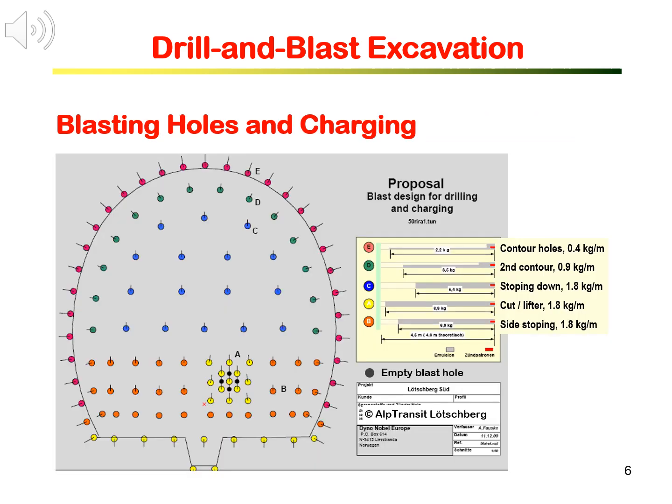With blast holes drilled, charging is to place explosives and detonators in the holes. Blasting is well designed in terms of time delay and the charging quantity. The figure here is the blast design of drilling and the charging of a rock tunnel.